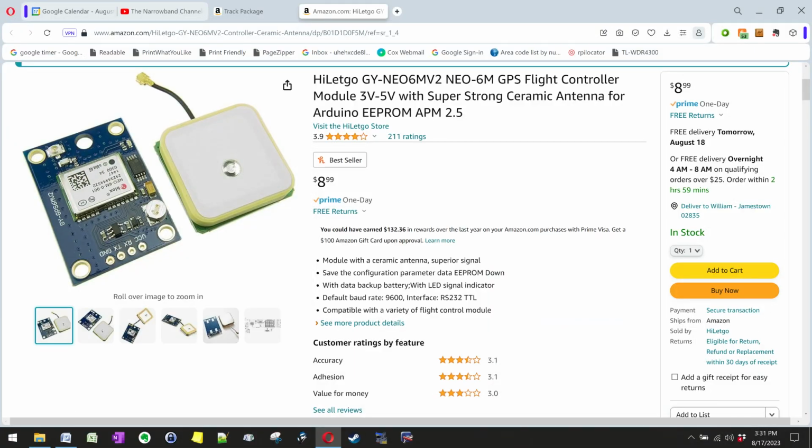The list of modules that make the astronomer's compass possible begins with the GPS module. This module provides the location data. As a bonus, it also provides coordinated universal time, eliminating the need for a single-function real-time clock. GPS is free-running, providing a continuous stream of data, and the Nano can just listen without soliciting the data.